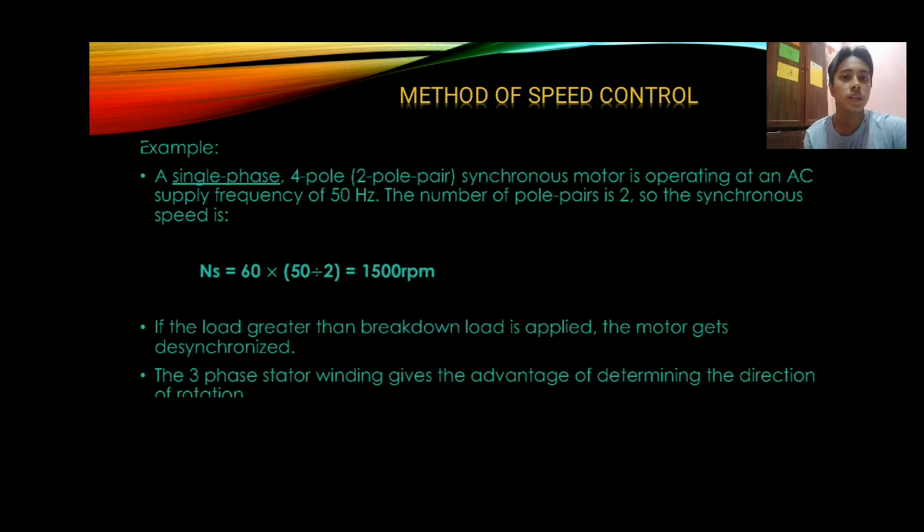Next, it's still the same method of synchronicity. This is what I said earlier. If a load greater than the breakdown load is applied, the motor gets desynchronized. It means there is a repulsive force between the RMF and the rotor.